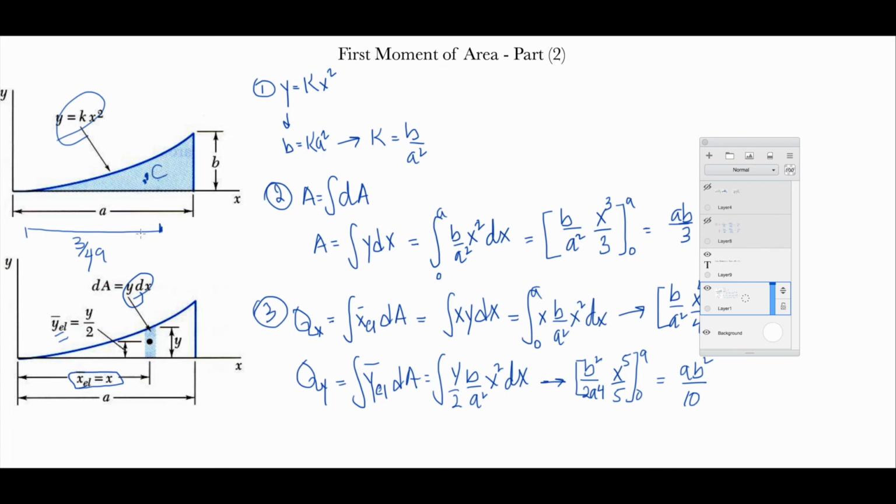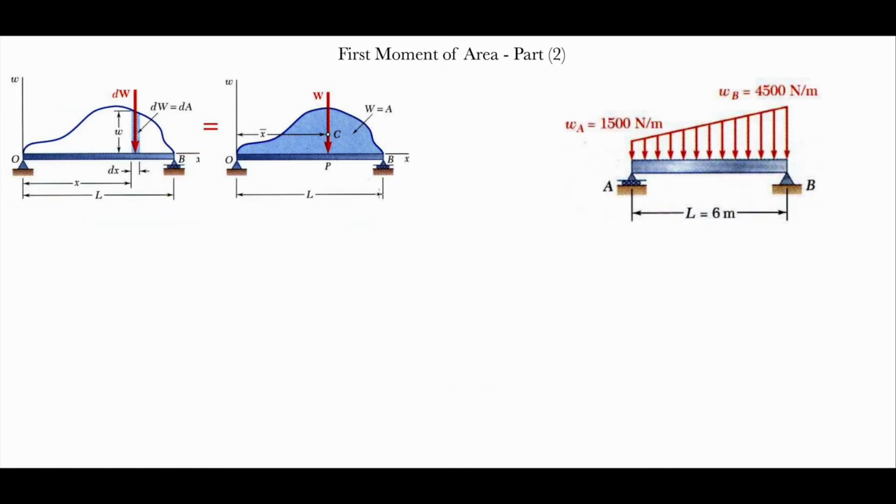Okay, let's take a quick application, which is if we have a beam. This is a regular shape. Again, this is what I explained, that if we have a regular shape, we need to find the equivalent load. And then with this equivalent load, we will find the A and B, or O and B reactions. And finding this is with the integration, as we said. We take a strip and then do the integration with respect to the x. That's what we said.